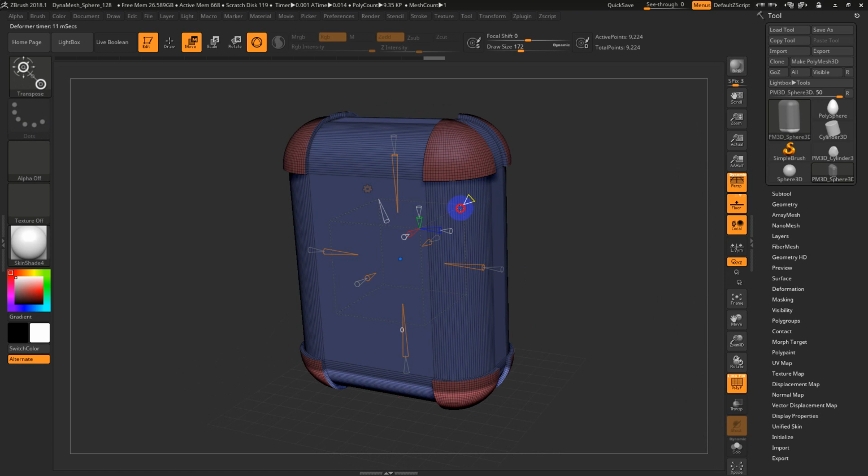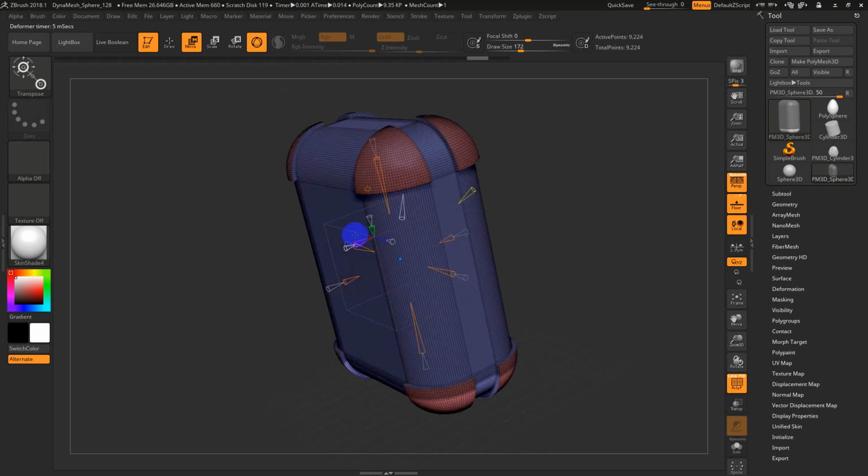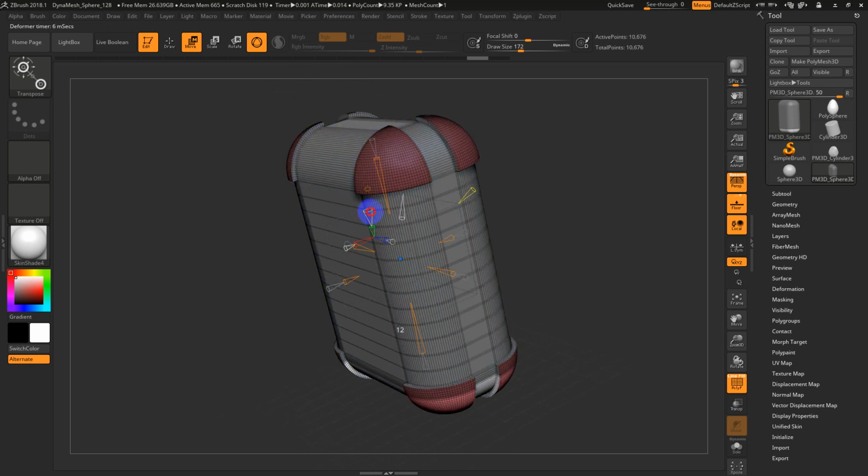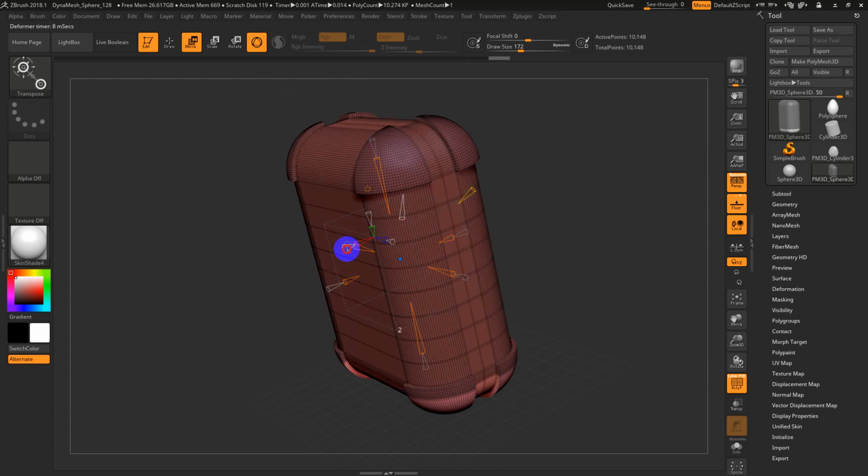And we also have a creasing option. I'll talk a little bit about creasing later on. And then we can also, I believe, where is it? I want to affect the poly count or the resolution. So yeah, it's on the XYZ. So you can actually increase the number of polys that happen in between the extension, essentially. Okay, so we can have more divisions on the side. I usually like to have a roughly equal amount of polys depending on what I'm doing. Right?